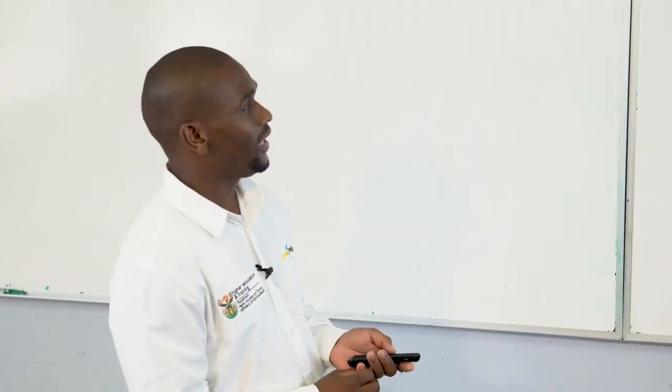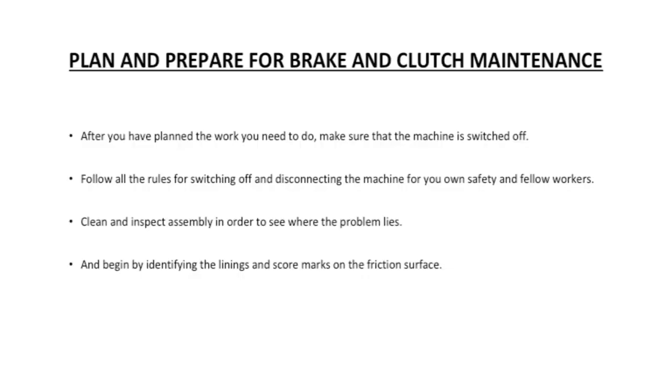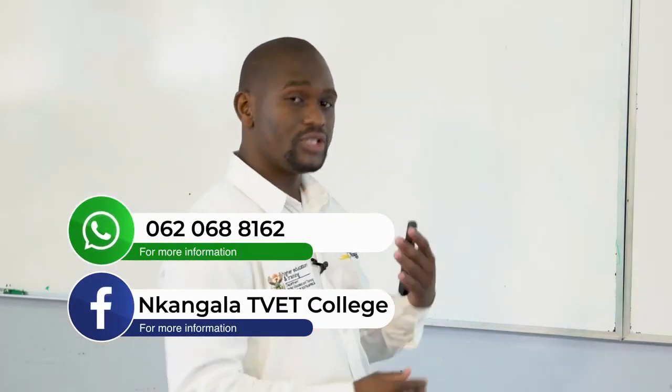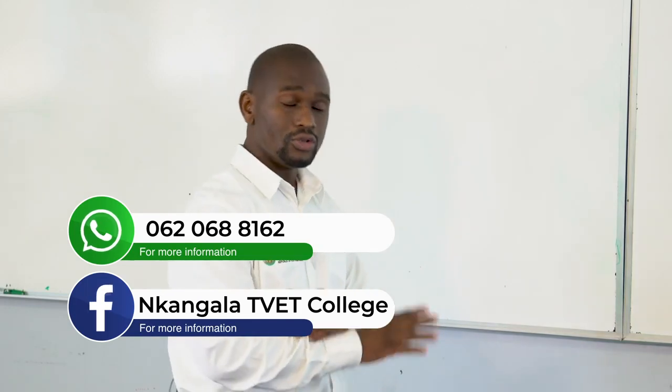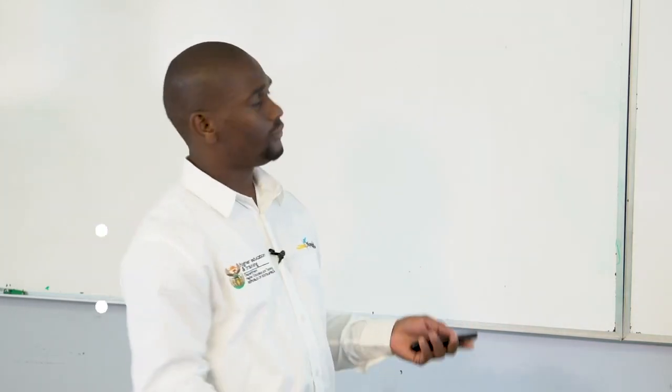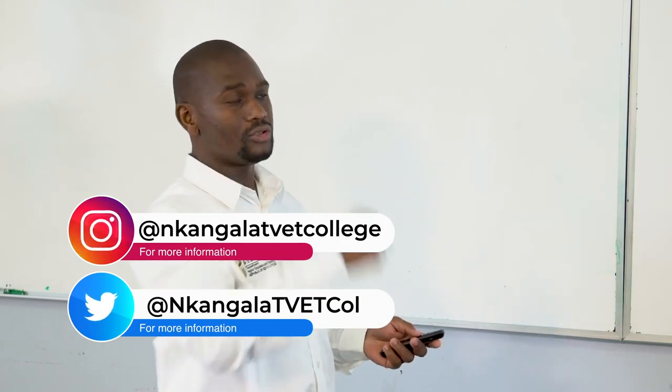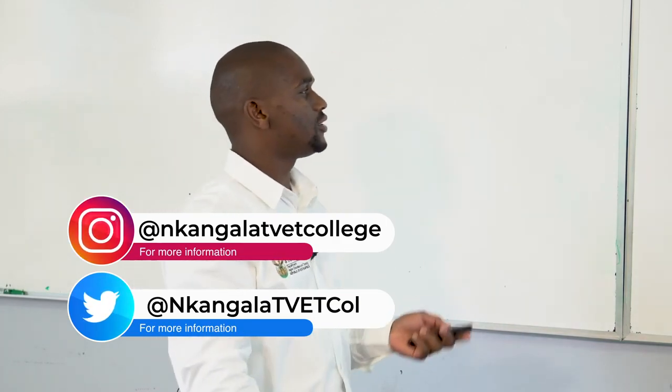Now we have to plan and prepare for brake and clutch maintenance. What is it that we must do? They say after you have planned the work, you need to make sure that the machine is switched off. Before doing any maintenance on brakes and clutches, make sure that your machine is switched off. I'm talking about from the power, from the main source to the machine. Make sure that is off.